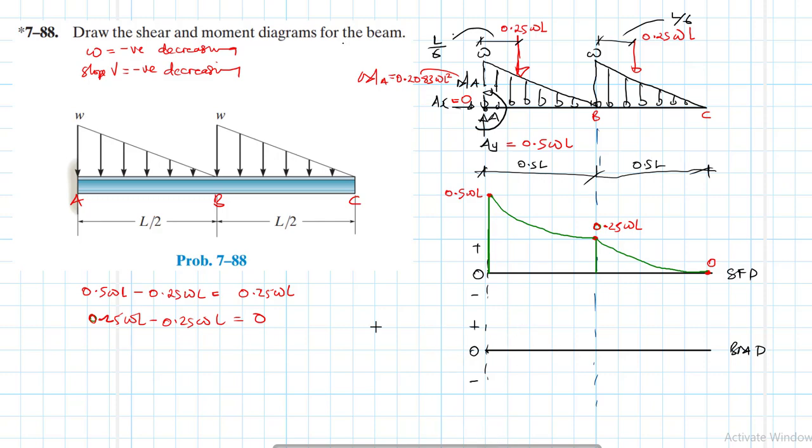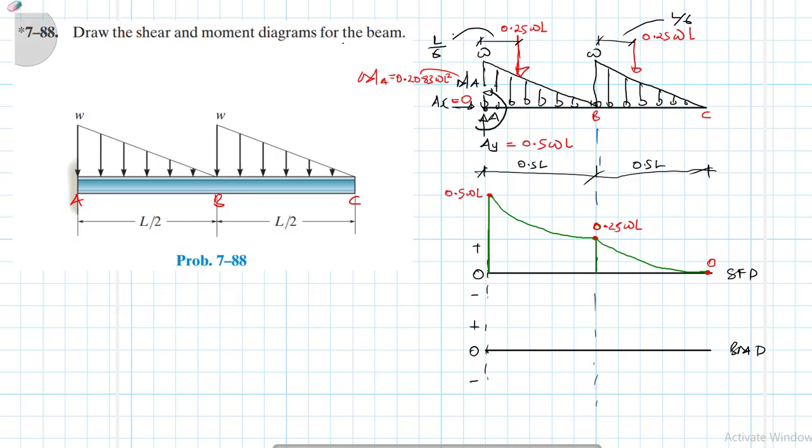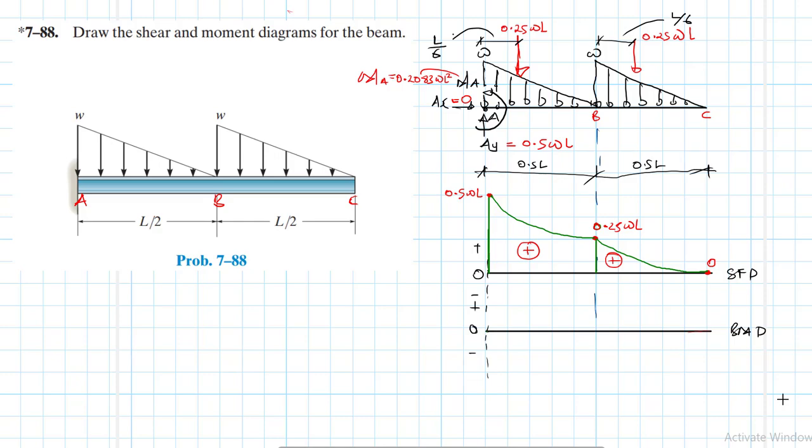So for the bending moment diagram, let's go ahead and work it out. Let's now draw the bending moment diagram. We are done with the shear force diagram, and like we did for the shear force diagram, we didn't do any sectioning. Rather, we were using the differential equation that relates the distributed loading to the shear and to the moment.